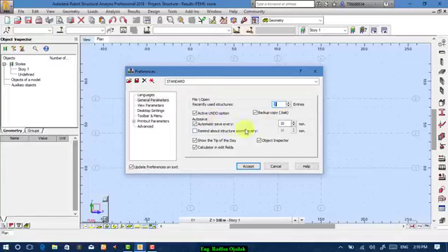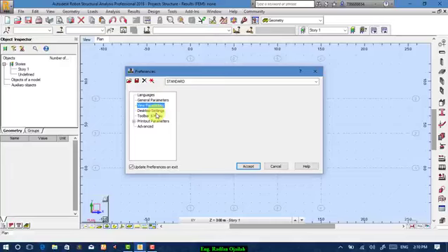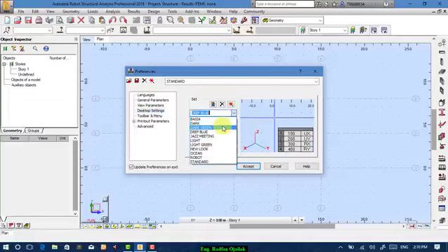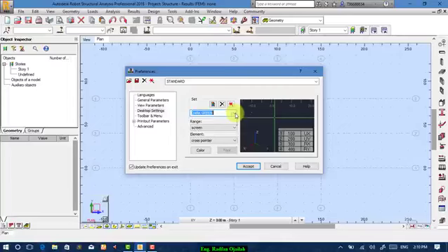And autosave, you can change it to, for example, 5 minutes, if you're working on battery and sometimes the battery will go dead suddenly without telling you. And view parameters, don't change that. And from here, desktop settings, you can change the color of the background from here, for example, deep blue or dark green or something like that.